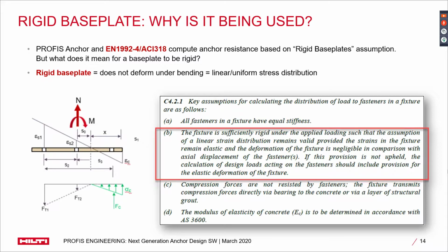This is commonly known as the elastic theory and is used to simplify the connection and calculation of the loads on the anchors. Importantly, this elastic theory is used for the derivation of many concrete failure modes to do with the concrete capacity method, which the majority of anchor codes are based on. The significance is that a rigid base plate is also a requirement of ACI and European guidelines and most post-installed anchoring standards.